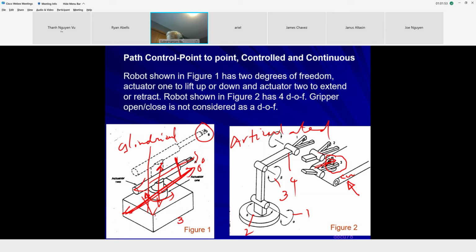Now comes the problem of not being able to adjust. It's mechanically adjusted to go to position 3, so it's very fixed to do the automation in this task. It moves up, then it extends. This gripper must be open. The gripper is not a degree of freedom; it's either open or closed in this case. So it extends with the gripper open, then it has to lower from wherever it is to this position. That tells you the home position must be at this height. Then it closes the gripper, lifts up, retracts, rotates, and throws it on another conveyor that is here.